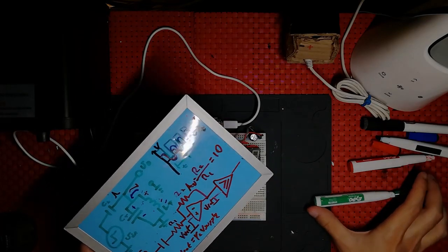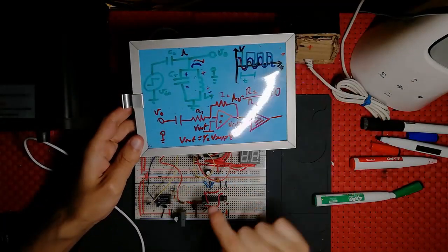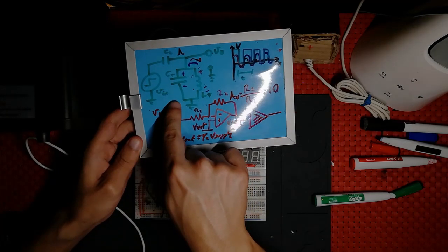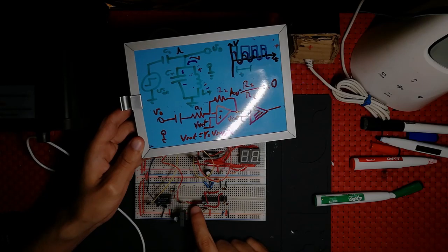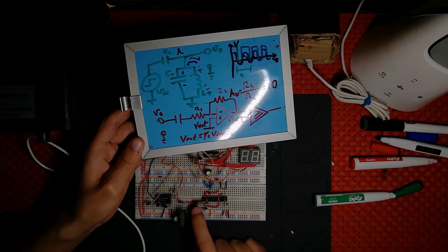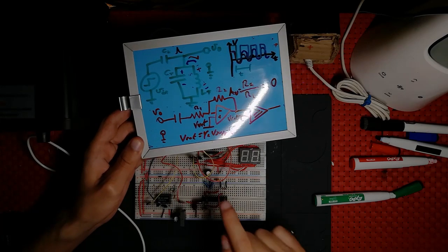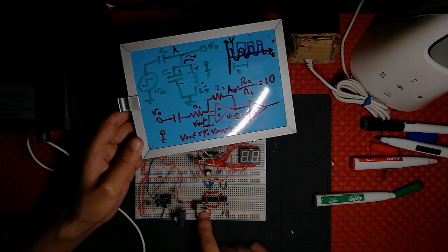So let me show you the circuitry right now. Okay, so this part in green is this bit over here. This is CT in this circuit. This over here is CV, and this is the test inductance. This is the DC blocking capacitor here, which will go on value. These are the resistors for the gain.